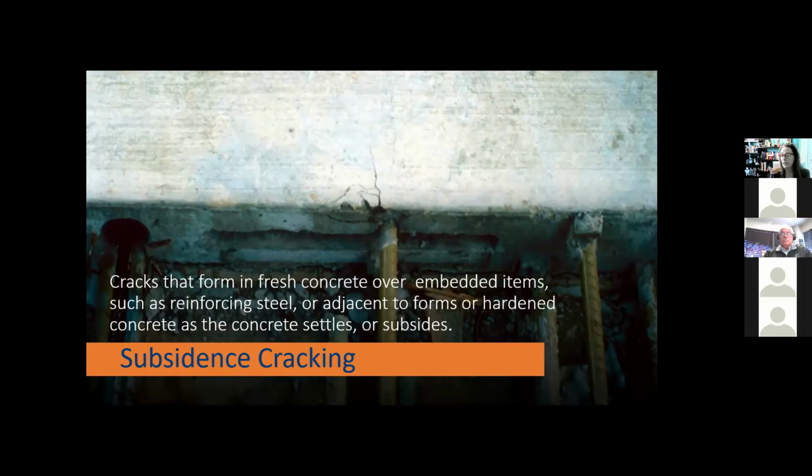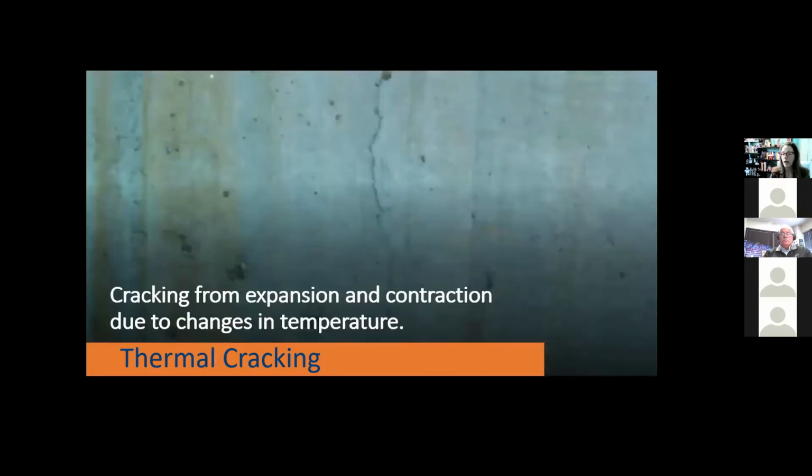With that said, we definitely want to reconsolidate over reinforcing while it's still in its fresh state. Make sure that's well consolidated at that stage. Just finishing over this type of tension, if you see it, and I'm not sure that you'd actually see it till after the concrete's hardened, will only cause the crack to be covered and it would still be open underneath. So the prevention here is proper consolidation of flat work, which is often ignored in our industry. So we do need to consider how you're going to consolidate around steel.